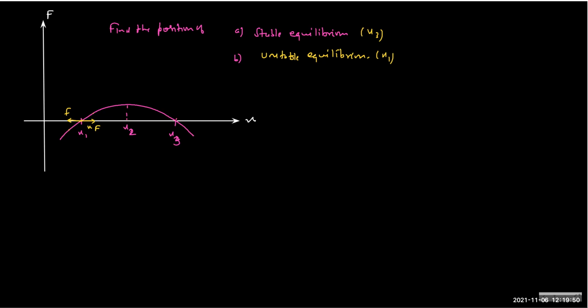Now look at the X3 position. If you try to go right, the force becomes negative, which means it is acting left. So your displacement is this, and the force acting is opposite, and vice versa. So if you go right or left, and the force is supporting the displacement, it means it's unstable. If you go right or left, and the restoring force is trying to bring you back, it is stable. This is one way of getting it.